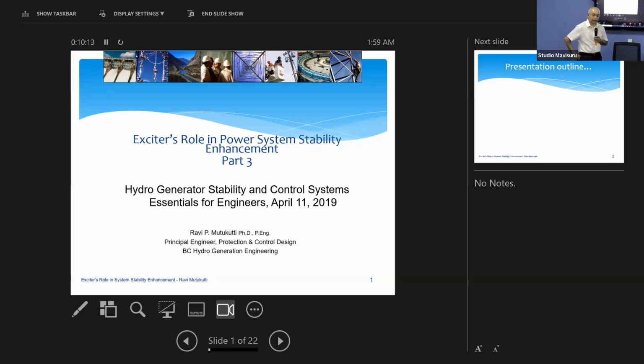4 of them were not tuned. 4 of them, the governors have problems, which need improvements in my opinion. I'm not sure whether it's already been done or not, but at that time it was the case. So I still believe that in the Sri Lankan power grid, you do have big frequency stability problems. So that's why you could not get that much IBR penetration.